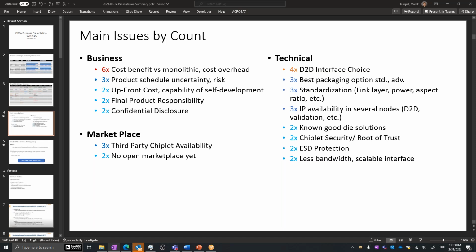Say for a monolithic die, typically it was okay. I'm going to put down this many SerDes lanes, and I'm going to be good. You design your die, and then you still have the option to modify the package to some extent: how many layers you would need, what kind of substrate. But now we are finding out that pretty much early on, when you're deciding on a product, you have to nail down what the substrate is.